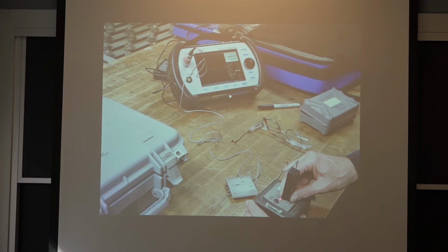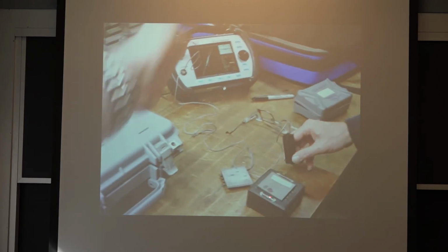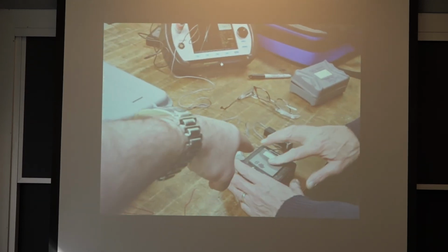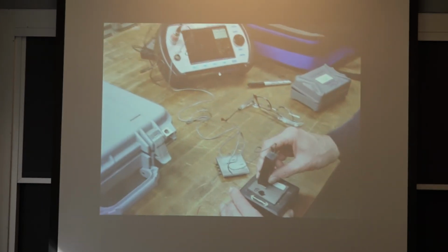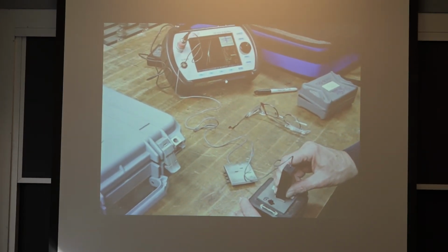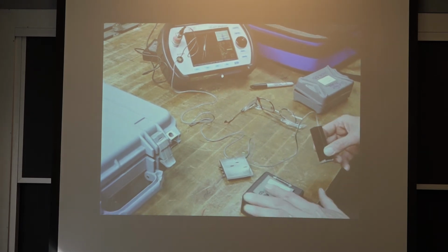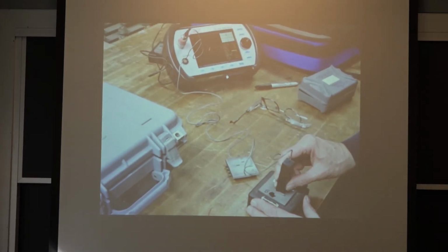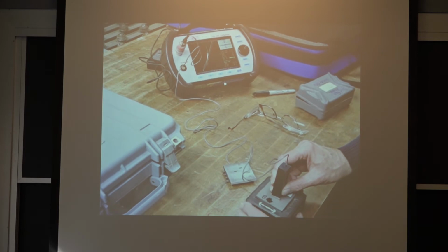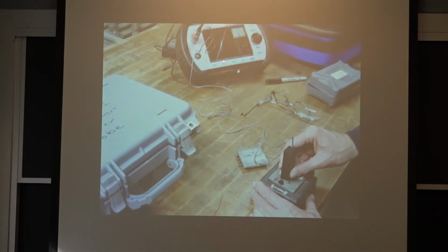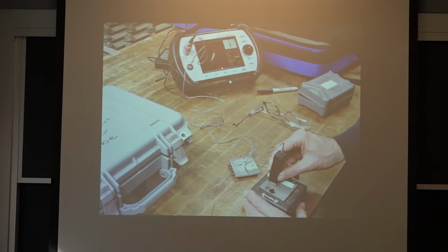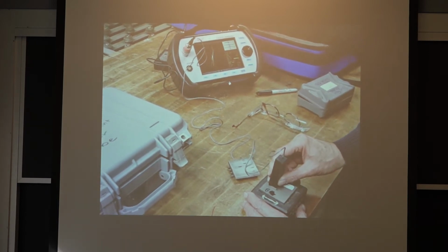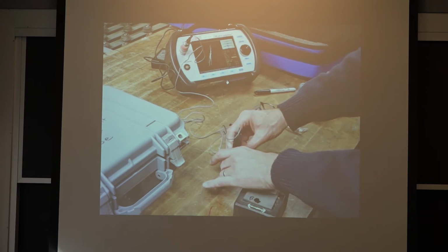as he's scanning over it. So is that telling you, since it's almost at a 45, that the notch isn't aligned to what your calibration is? No, it's not too much that. I think this is a wear spot. Yeah, lifts off a little bit. You're looking at a little bit of lift. So based on the scan here, he can tell that the data he's getting isn't relevant because of the liftoff.